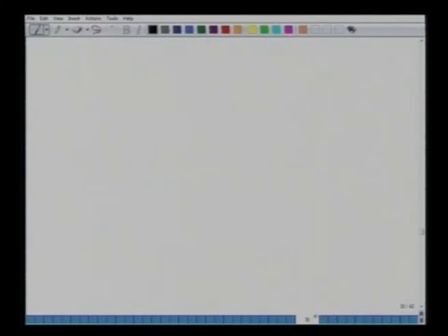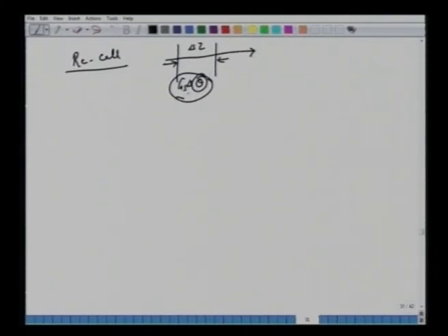If you go back and recall mass transfer, we talked about any small region del z. We are giving some residence time theta, so this Gs spends say del theta. We have so many kg of solid over this time del theta, so it's like a batch. Of course we have a continuous process where solid continuously flows like this, but we are saying that over del theta a certain batch of solid is getting heated. What we wrote in the case of mass transfer was Ky (Ys minus y), and we equated this to Ls del x del theta with Ls a prime. So we have the batch, and we are trying to make an analogy between the batch operation and the continuous one.